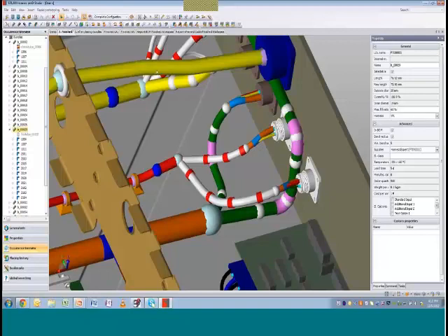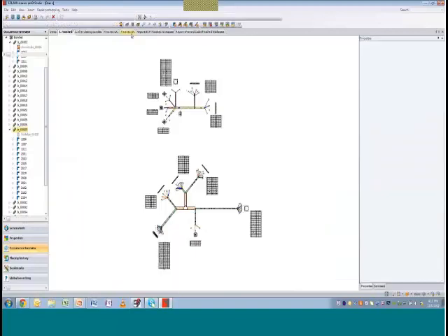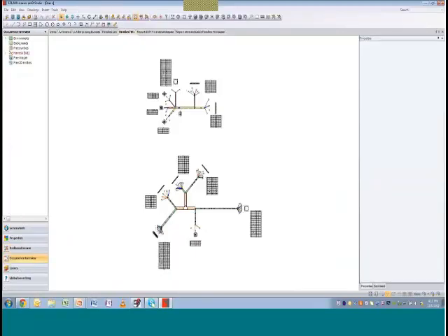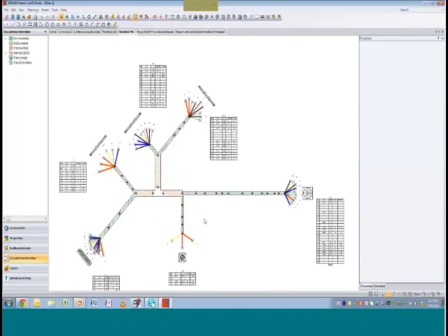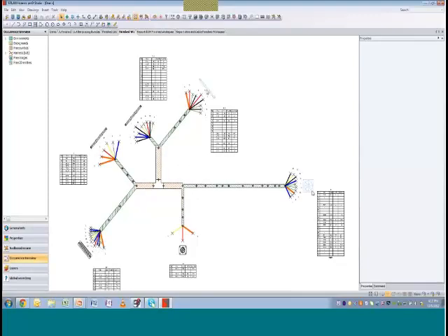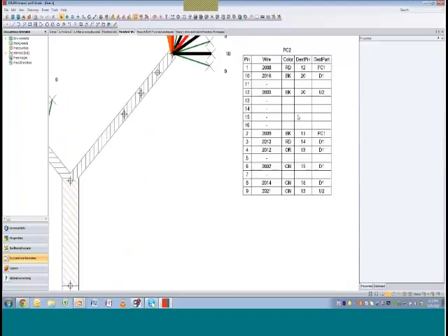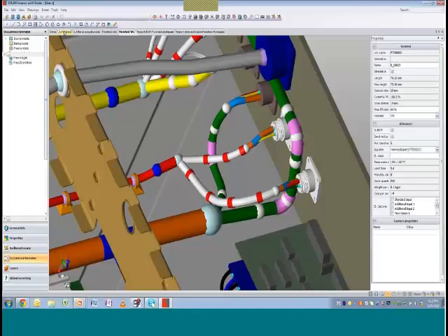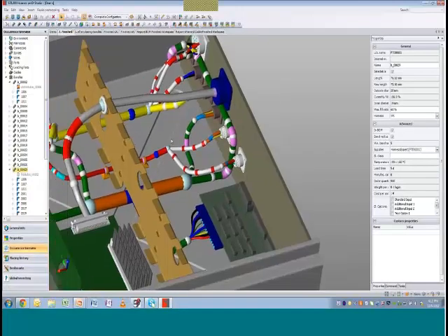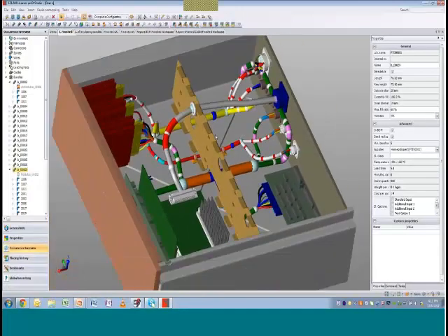We generate our nail board. Here's, for example, our nail board for our W1. You will be able to see all of the individual connectors for that harness W1, and also all of the individual connections. And what's nice too is you have a little table here that you can quickly identify. This box is essentially my finished product. Okay, and I'm going to show you here in a few minutes how we got here. How did we get to the finished product?